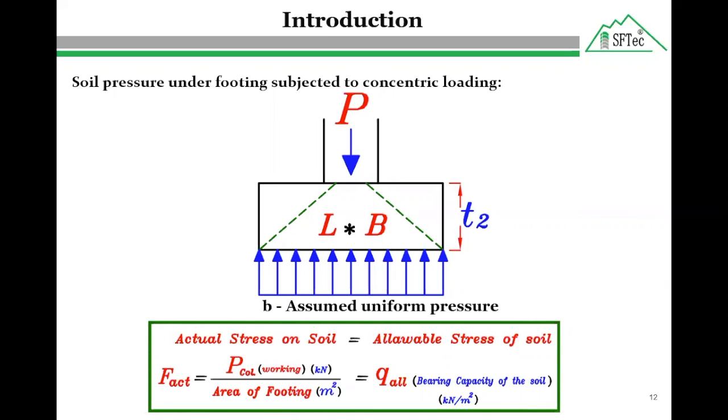This is a very important question. As known, the fiber in our rebar is in one direction. The effect of having the fiber in one direction gives us a linear stress-strain curve up to failure. However, if we include another fiber orientation, like I saw in some patents dealing with this kind of orientation, you will have a plateau similar to the yielding plateau of the steel bar.